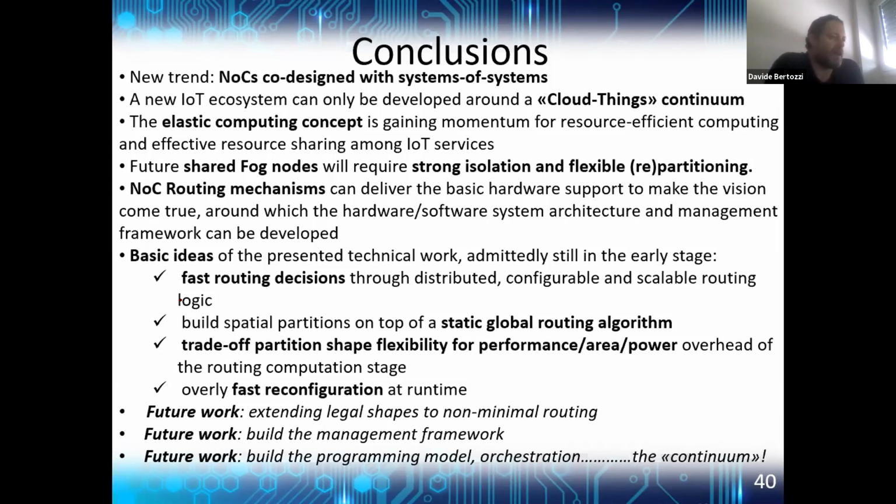Overall, this LBDR approach is a trade-off between shape flexibility and performance, area and power overhead of your routing computation stage, and it enables very fast runtime reconfiguration. Only 4 bits to be reprogrammed for every switch.